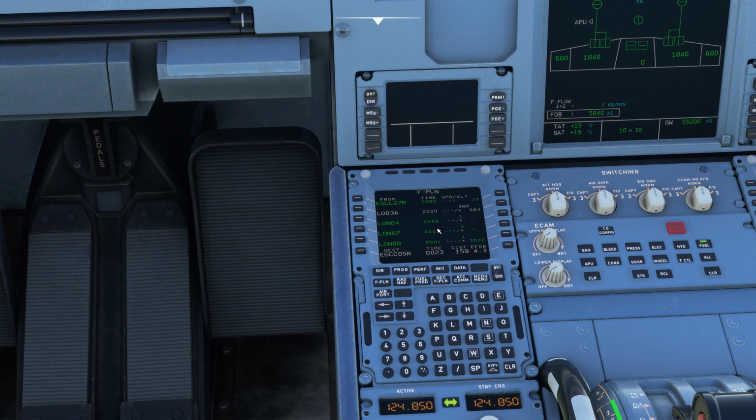So I'll just give a basic rundown of how to make changes on here. Again, you've got all the points here. If you did need to clear something, you do as we did before, you press clear and clear it. What I'm going to do first of all is show you entering another waypoint into this flight plan. Let's just go for the USR waypoint that we removed before. So USR, I'm going to click TNT because I want it in between Welling and TNT.